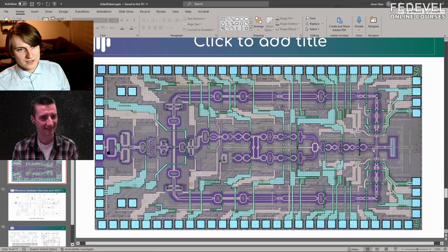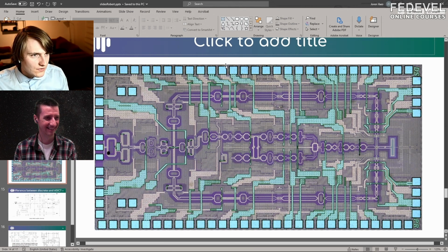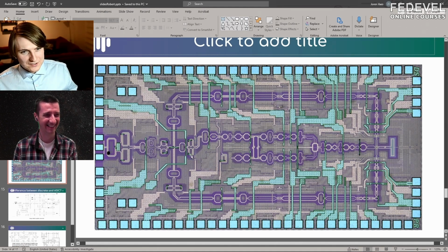This is a receiver, right? And then you have, here is a mixer. You have some amplifiers. You have an IQ demodulator as an IF, and then you go down. And I guess the output flows somewhere here, because then this is the LO chain. So you probably have two other mixers here somewhere. Dragon, don't hate me if I get this wrong. But this is what we design.